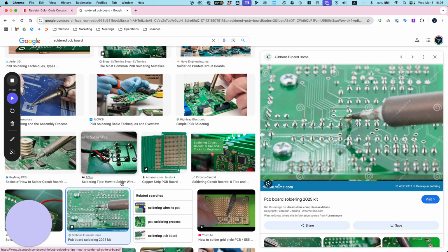Okay, so if you look at this slot, the slot on this LED is kind of going down to the bottom right, right? You see that? It's angling this way. So I need to also angle it this way, like this. If you recall, each of these columns are connected. So A is connected to anything on A. We have B's and C's. So the next one, I want to connect this LED to the previous one on column C.